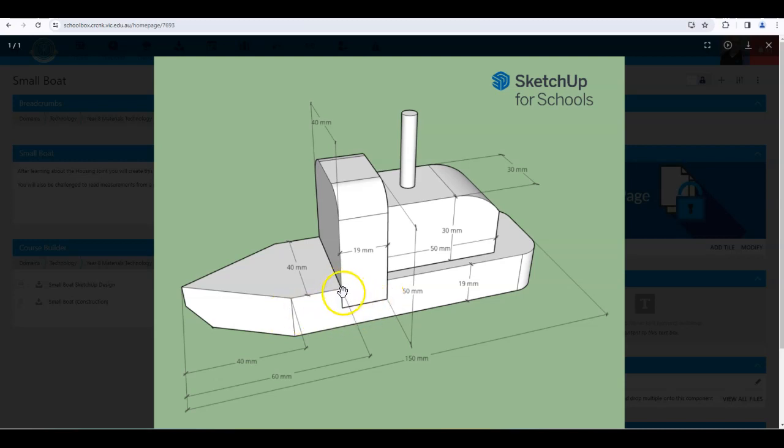So this housing joint is very much like a rebate joint that we've done previously, but because it's not on the end of a piece of wood, it's somewhere in the middle part of it. We now call it a housing joint, but the basic idea is the same. We're going to create a gap that is as wide as the piece going in, so in this case 19, and it's also going to go halfway down. So what was 19 here means that this part must be going down 9.5.